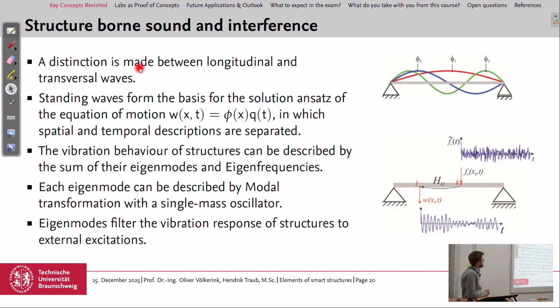Then today we started with structure-borne sound and interference. We made a distinction between longitudinal and transversal waves, and had this small experiment for longitudinal waves here in the lecture. And we got to know that standing waves form the basis of the solution ansatz with the separation ansatz, where we have the solution for the equation of motion consisting of 2 parts, the spatial and the temporal description. The vibration behavior of structures can then be described by the sum of their eigenmodes and eigenfrequencies.